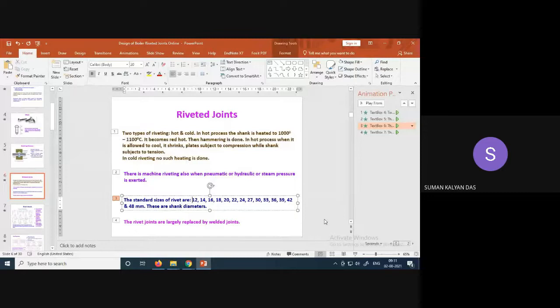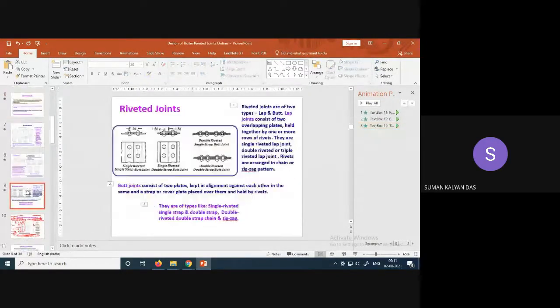বোঝা গেল? So this is one thing you have to remember. Standard component ক্ষেত্রে, be it rivet or be it bolts, you have to select the standard size of that corresponding thing from the available table or catalog, and then you have to finally report your answer. So this is one thing I missed.